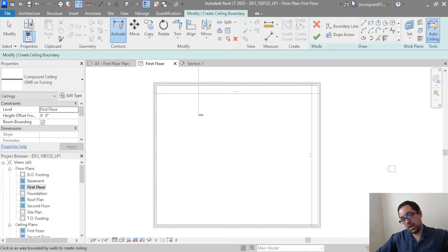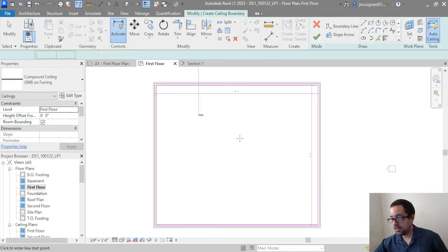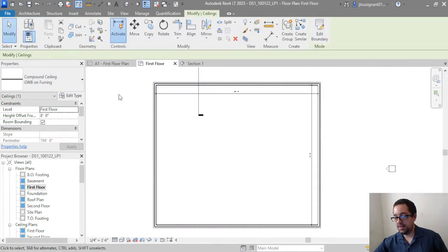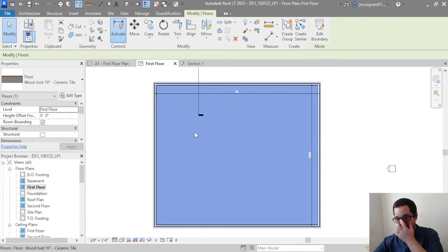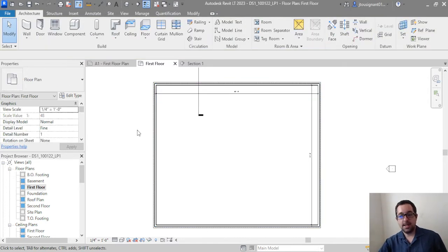So we're going to go ahead and try to place this automatic ceiling though, because our view range is allowing us to place an 8 foot. So I'm just going to place and click in this room. That's going to place the automatic ceiling boundary tool, and I can press check and it's going to have it placed. Now, when I click, I'm not going to click on the ceiling because I'm looking down, because Revit prefers you to be in a floor plane when you're building this ceiling.